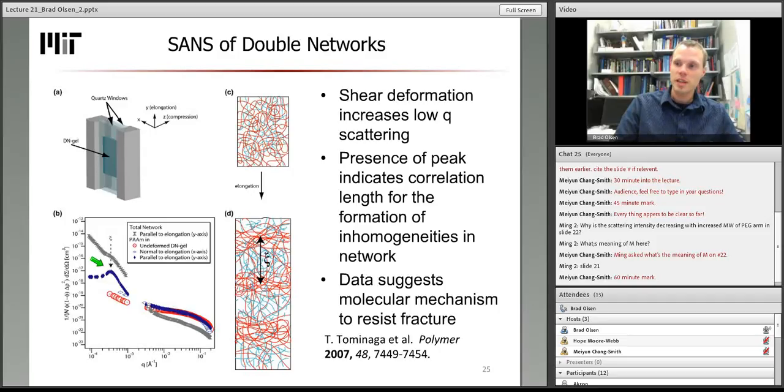Because the gel was chemically bonded, to form these structures, you need to break chemical bonds. And breaking these chemical bonds will dissipate a lot of energy, but the chemical bonds won't reform when this compression is removed. So when the compression is removed, the intact network pulls the gel back together, but the second network has already been broken.